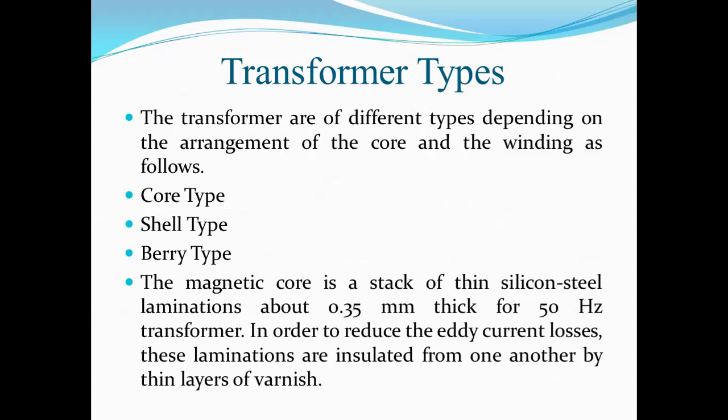So next, this flux flowing through the magnetic core of the transformer links with the secondary winding, means flux is cut by the secondary winding conductors. Then in secondary winding conductors also some EMF is induced. That EMF is known as mutual induced EMF. This total process is known as the working principle of the transformer, the mutual induction principle.